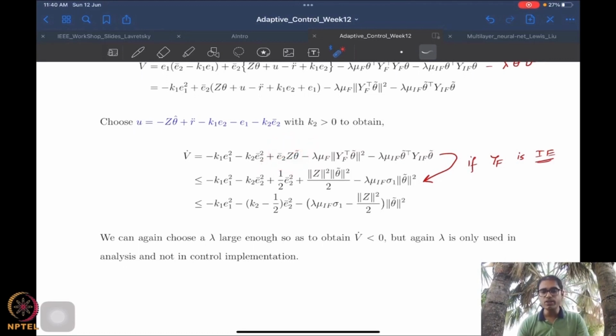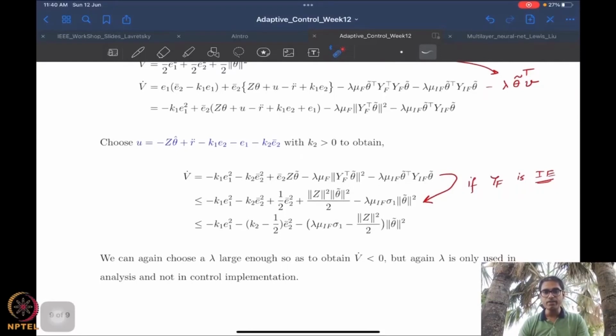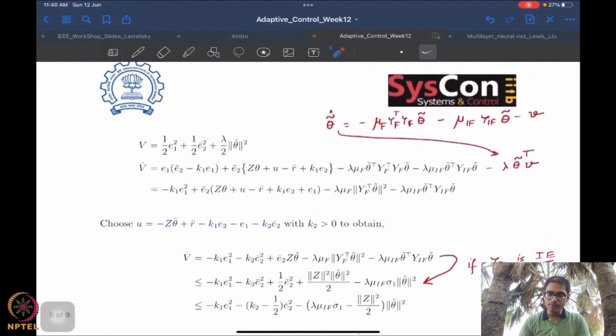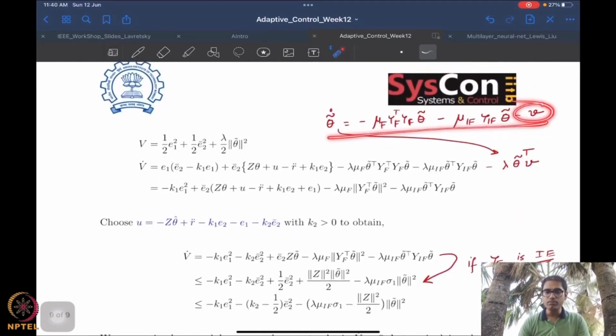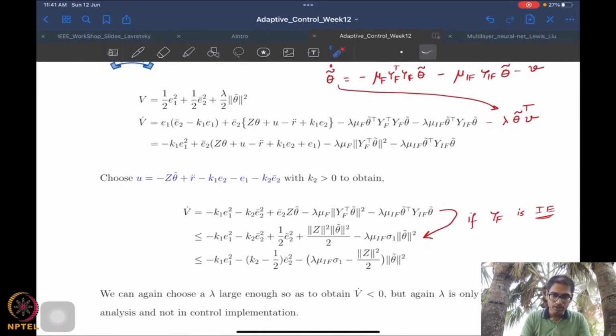And that's what we're trying to do. Okay. So if there is excitation, everything was nice, excellent result. But in the absence of excitation, we want to make a modification to the adaptive law so that I don't have to deal with this mixed term, which I cannot cancel or dominate anymore. Okay. So then I propose this sort of additional term and I try to see what this additional term will be. The additional term has to come from the Lyapunov analysis. So this term remains as it is here.